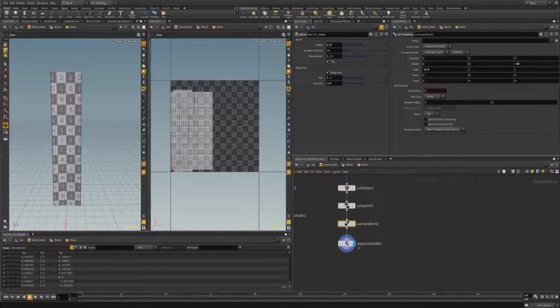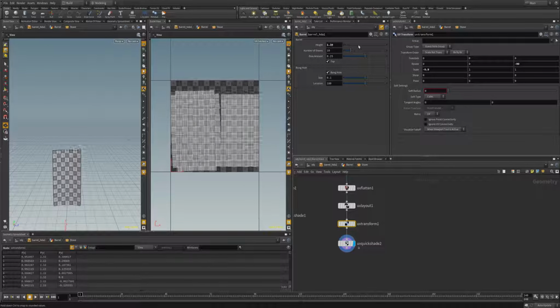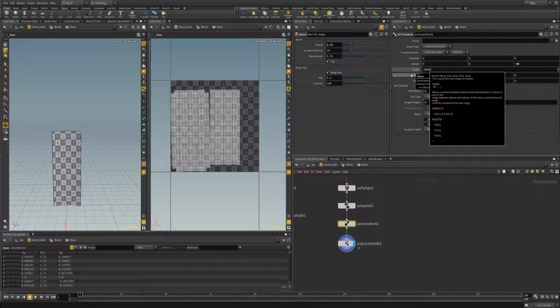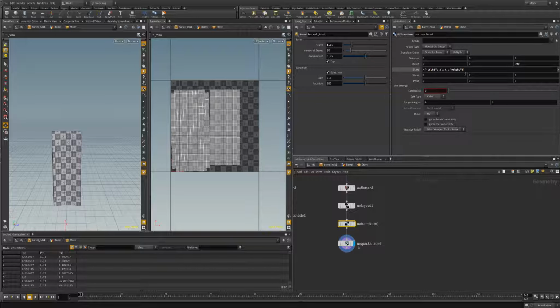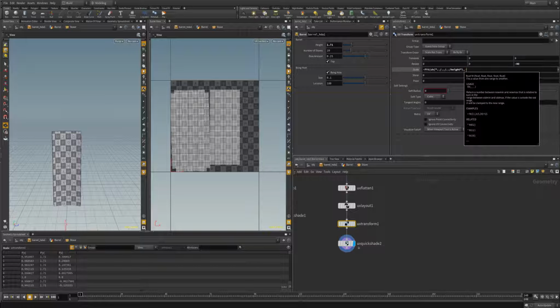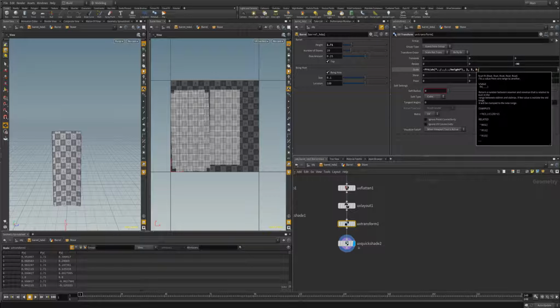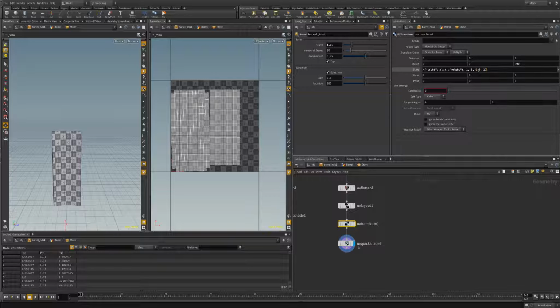as our stave increases in height. And to do that, we actually can use the fit function and rescale this on a range of 0 to 1 based off of my height. So I'm actually going to copy my height parameter here, and we'll do a negative fit because I still need it to go in the negative direction. And I'm going to paste my reference to my height, and we'll go from 1 to 5 because that's the min and max parameters of my height parameter. And we'll go from something like 0.5 to 1. Like that.